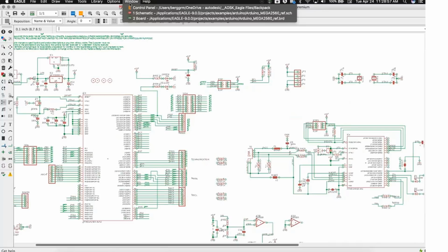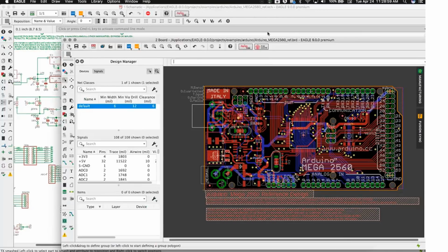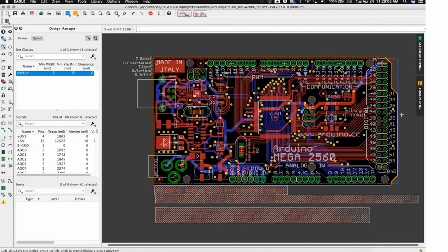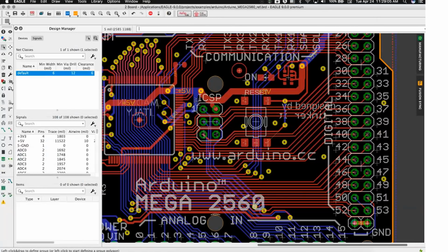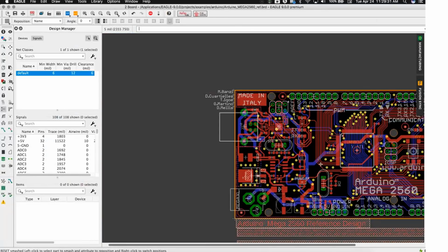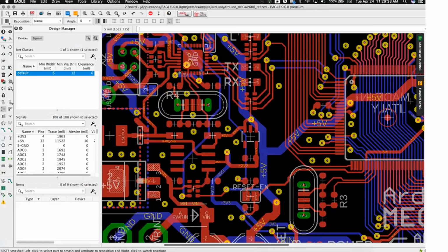So, if I bounce over to PCB here for a second, the same rules apply in PCB. If I need to position component text, component designator, any of those sorts of things, again, the Reposition Attributes command is available in PCB. I can choose either name, value, or name and value. And depending on the position that I choose, I can push part position or push designator information somewhere around the outside of the part itself. So if I decide that I want to move this down here, I can move all of those things around very, very quickly and easily. Really simple, easy way to go ahead and clean up your design.